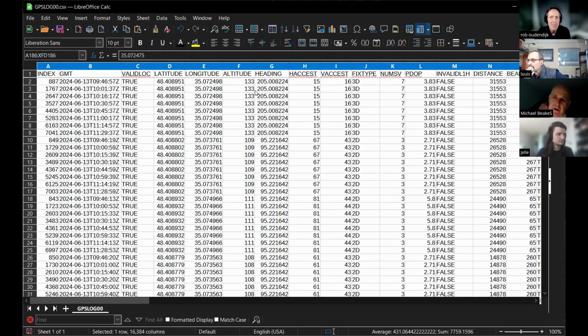The UBX log that you can generate from the tool is the same file. You just rename it in the SD card to UBX input.hex. Then you go into the settings and say, for emulator, I want to use the SD card, and it'll use that file and just replay it. It gets the timestamp from the very first entry in the file, and as it loops around, it just keeps incrementing the timestamp. But the first run through, the timestamp will match your original log file.